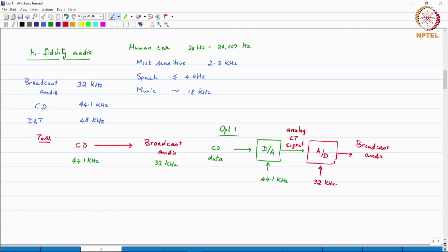So, this is a very simple practical application where you are forced to convert. Now, notice that any time there is a conversion from digital to analog and from analog to digital, there is some loss of information and some loss of fidelity. First and foremost, there is some complexity involved, because D2As and A to Ds are running. D2As and A to Ds actually have analog filters in them.